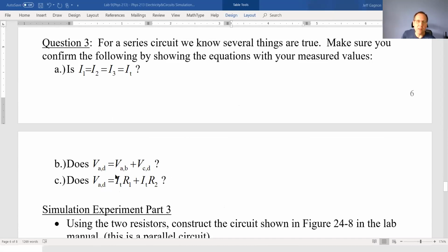And then this is sort of almost the same question here. Another way of writing the voltage drop across AB is using Ohm's law. We can rearrange it and we can say that the delta V, the voltage drop, is the current times the resistance. So if I take my I total and then multiply by R1, because remember, I total is the same, the current's the same throughout the entire circuit. So this is like the current that goes through R1 times R1.